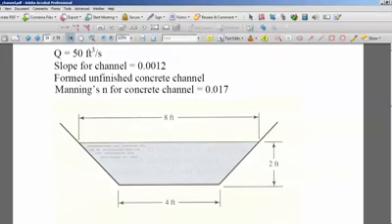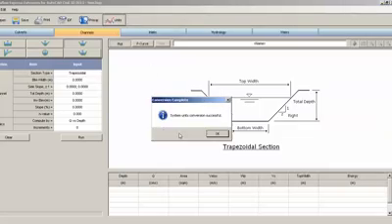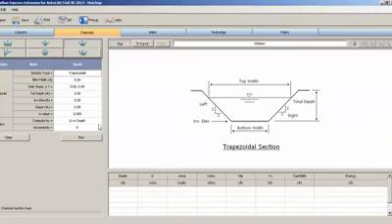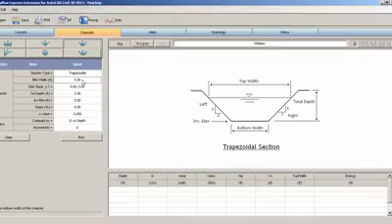First, we have to set the unit. We have here feet, and here we have meters. So there is a unit here; you can change or convert it. Here it is feet now. For the section type, we have to put the trapezoidal channel, and the bottom width is this one. We have here 4 feet, so alright, 4 feet.